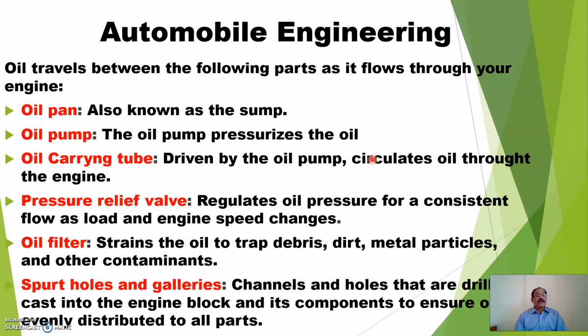Then the oil filter, because every time the oil circulates through the engine, it carries some dust, wear particles or debris from the components, and they are all collected in the oil pan. When oil is again lifted by the pump, it is necessary to filter it. So oil filters are necessary to remove the dirt, debris, metal particles and other contaminants.